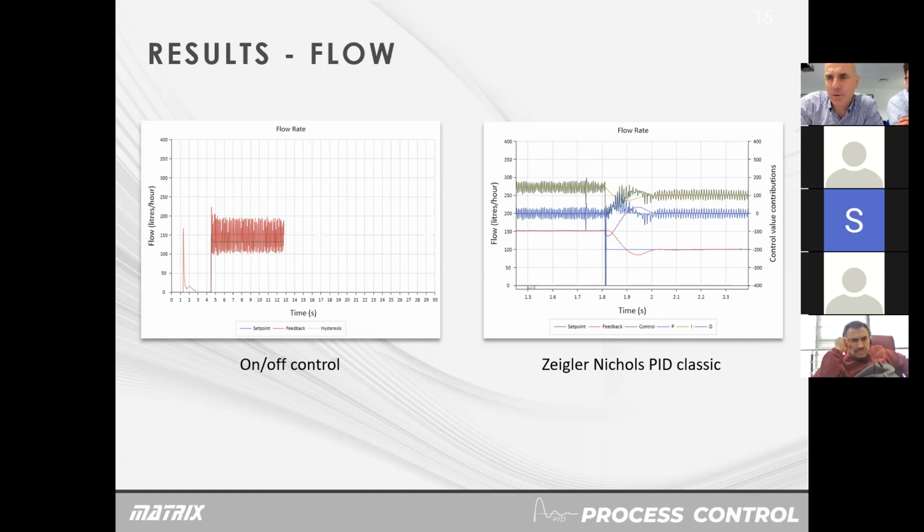Now, Ziegler-Nichols were a couple of engineers, I think in the 1930s, who came up with some rules of thumb as to how you choose the values of Kp and Ki and Kd, the proportional, the integral, and the derivative controls to control process control systems. And they're sort of wet finger estimates, if you like, as to how you get these numbers. And so we put that in the manuals, and Ziegler-Nichols has several different types of control algorithm as to whether you want a little bit of overshoot and a fast response, or no overshoot and a slow response.